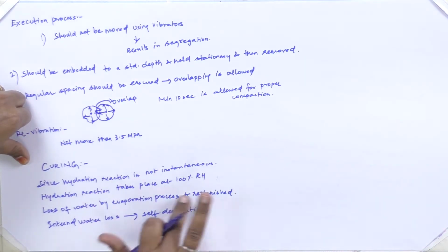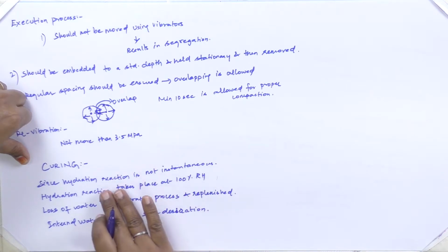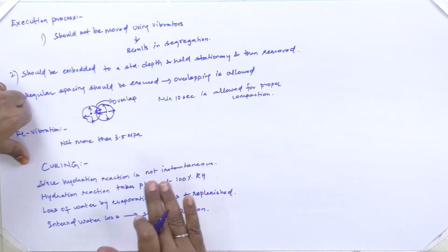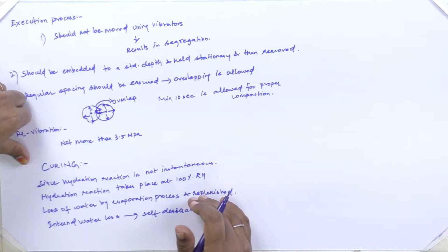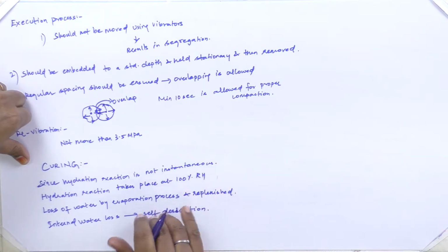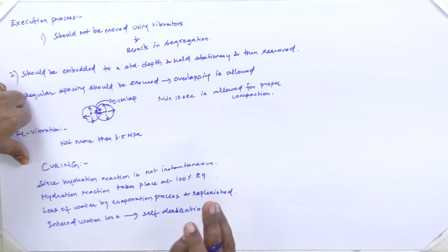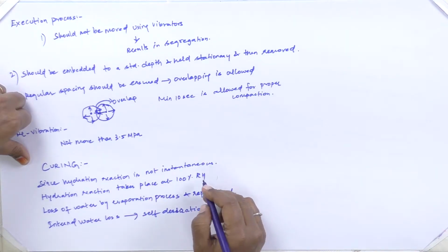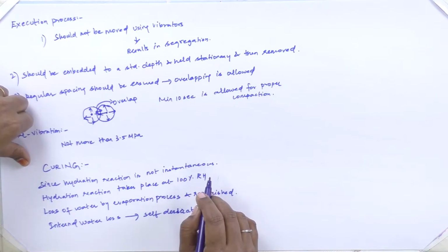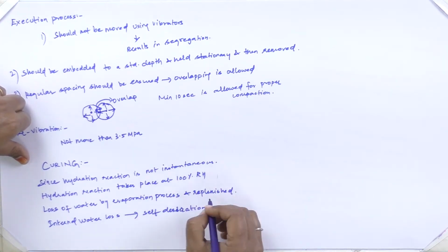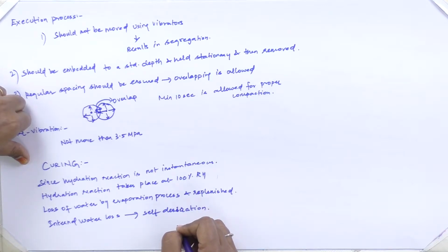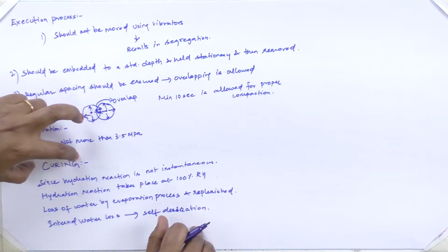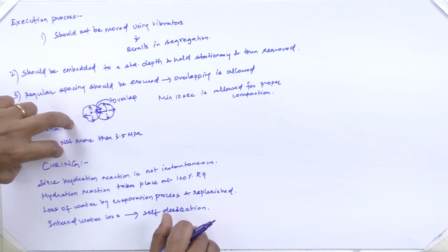Since hydration is a continuous process, during that process we have to see that the water which has initially gone in is not lost by any evaporation process or self-desiccation process. To prevent either evaporation or self-desiccation, we go in for this curing process.